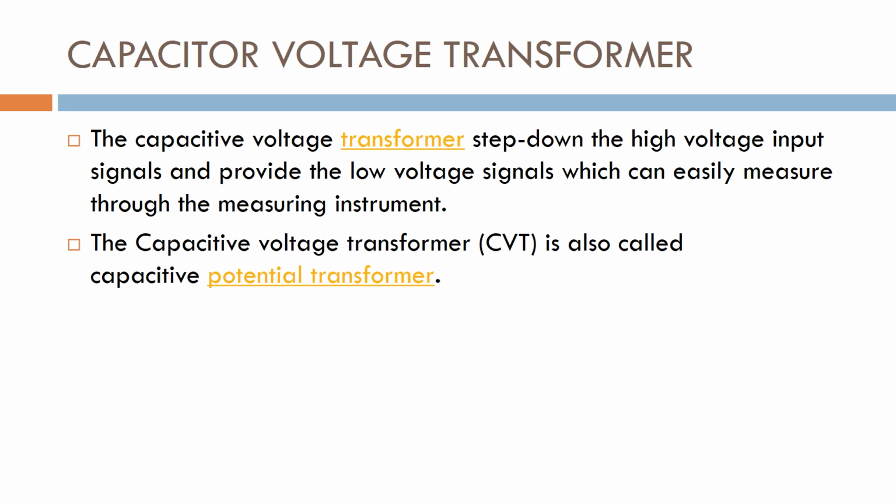A capacitive voltage transformer is a device used in power systems to measure voltages. It consists of a capacitive divider with a suitable matching or isolating potential transformer tuned for resonance condition. It can be connected to a low impedance device like the pressure coil of a voltmeter or a relay coil. It can supply a load of very few volt-amperes.